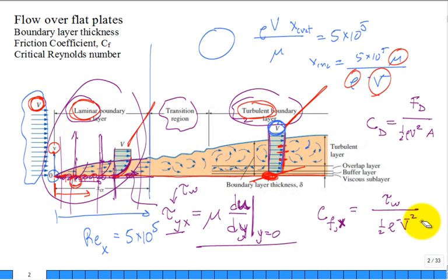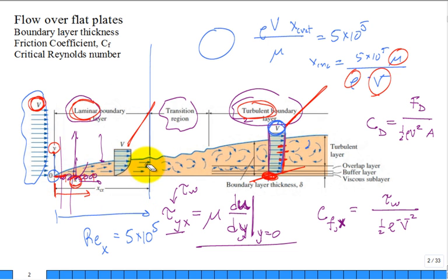And then one other thing is mathematically they introduce a symbol. Let me show it right here. It's a length, a distance, and they'll say delta. What is that? That's the thickness of this layer of fluid at the boundary, at the solid, which is significantly impacted by the presence of the solid. Okay, so they call that the boundary layer thickness. This boundary layer thickness, delta.